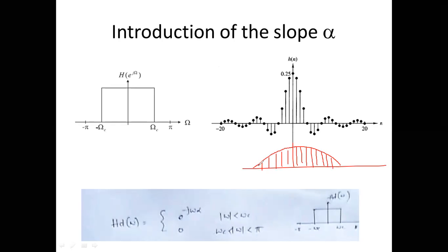Now since this is a very slow transition, there is a smoother cutoff, and you don't know when exactly it happened. So there is no abrupt termination, but there is a taper in the window. So as I said, what is windowing? Windowing is picking the finite values on the left and right side, but you don't do it abruptly.